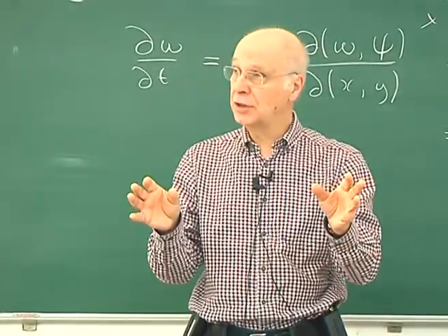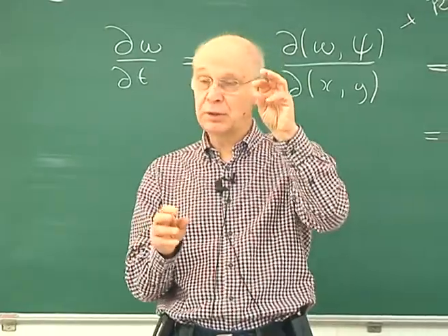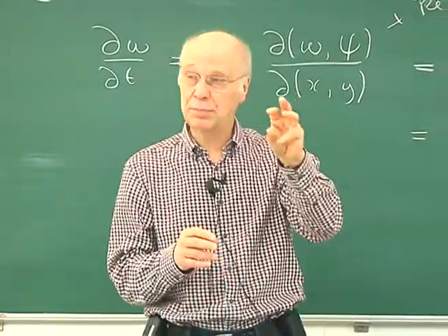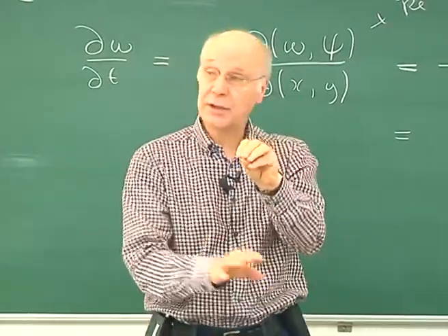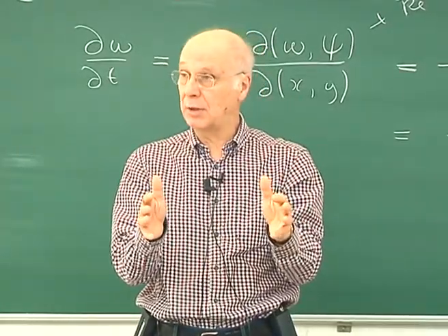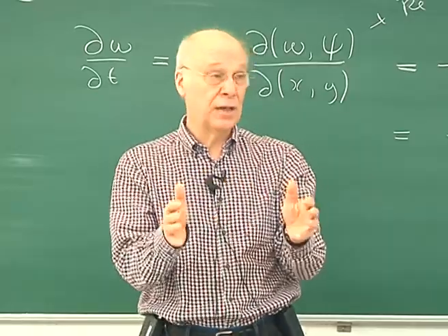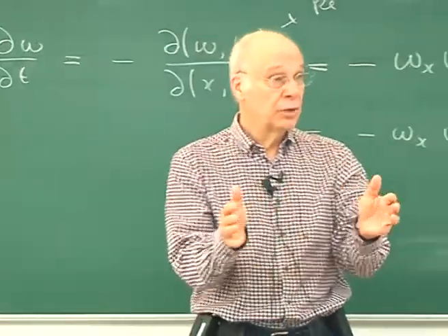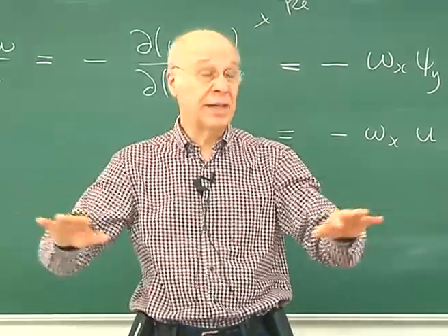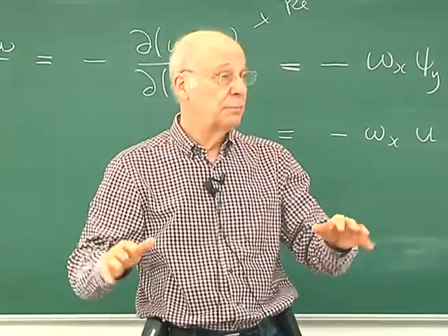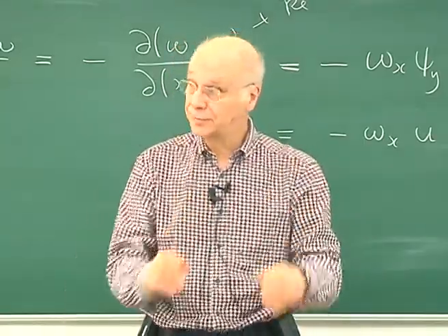And the basis function associated with a particular amplitude tends to be 0 almost everywhere, and it's just a couple of elements where they're non-zero. So it's a very localized representation. One particular basis function will vanish in most elements, but be non-zero in just a couple.